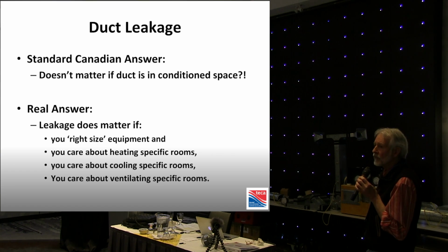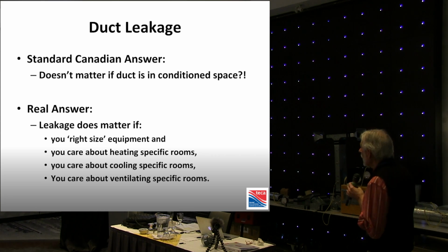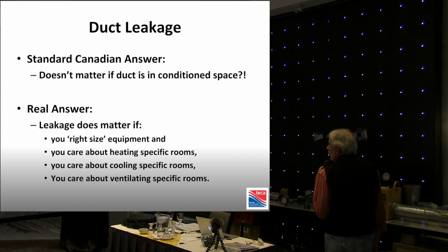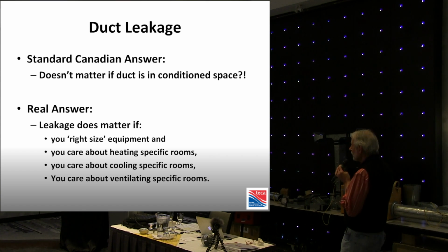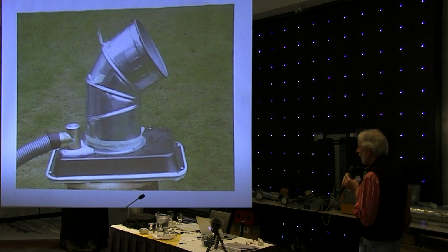Well, this blows up in our face if we start right-sizing. We start to want to get the proper number of BTUs to Mrs. Smith's bedroom, and losing 20 or 30% of it en route ain't going to cut it if we start sizing correctly. Real leakage does matter if you right-size equipment. You care about heating, cooling, or ventilating specific rooms.